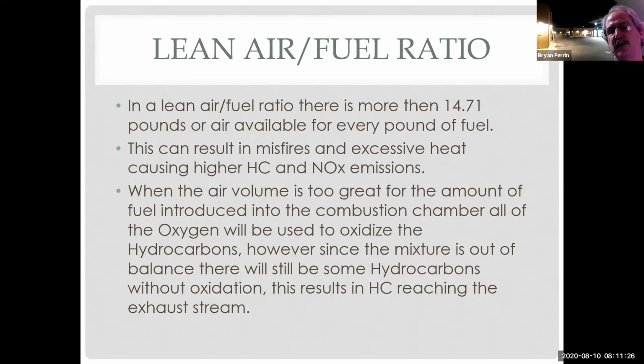So what happens is the oxygen and nitrogen become almost like an insulator around some of the hydrocarbon, to where the flame front can't get there, and therefore it doesn't burn. And that's why even with a lean mixture, even though I have plenty of oxygen to oxidize all the hydrocarbon, because of poor flame propagation, I cannot get to all the hydrocarbons to oxidize them, and therefore I'll end up with unburned fuel. We call that a misfire, or a lean misfire.